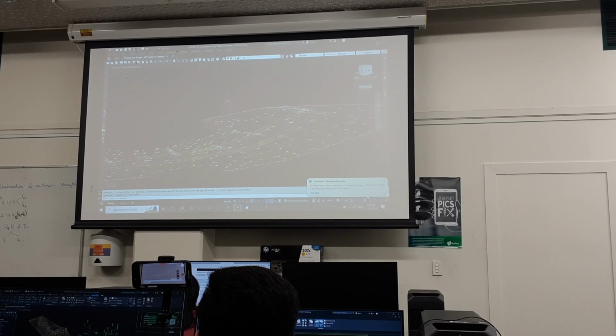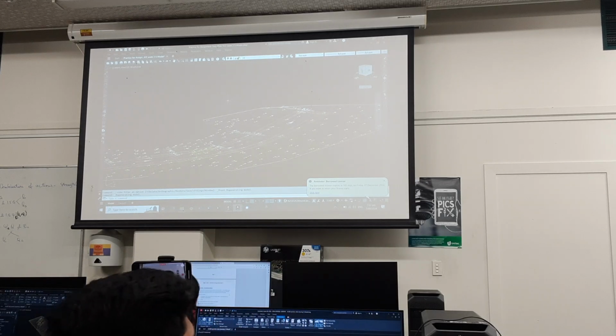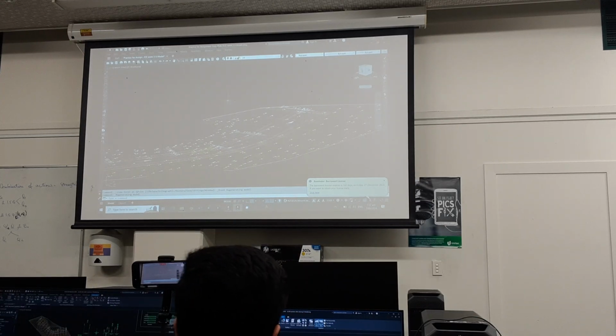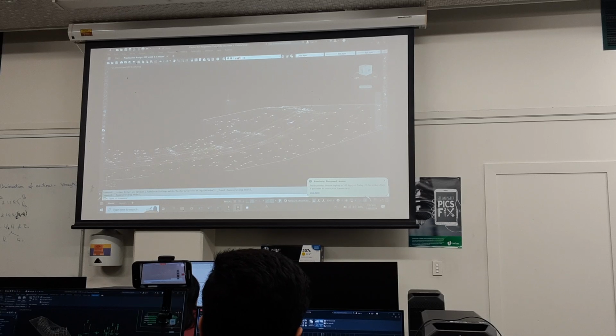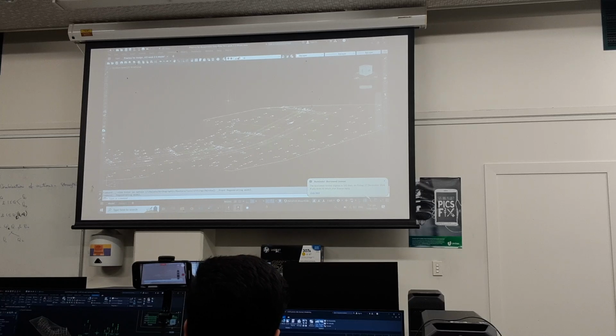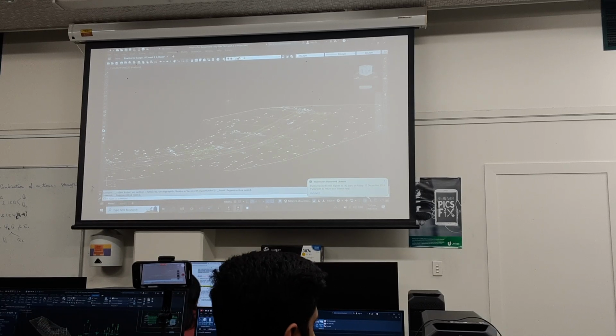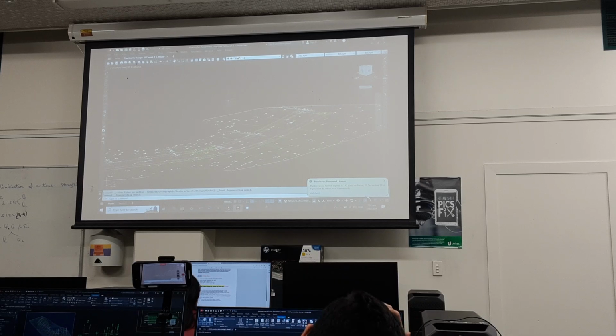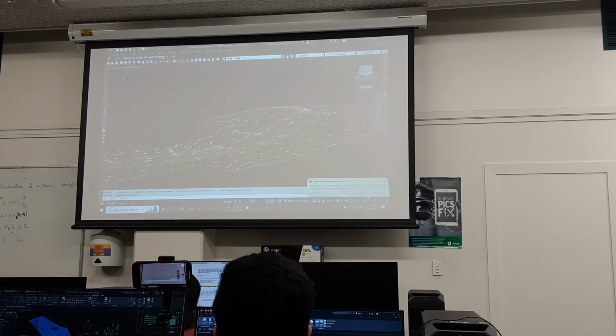Remember those lights that we clicked on before? On the left hand side we turn things visible on and off, and then do the export into AutoCAD. It will save you quite a bit of time in terms of deleting it from AutoCAD. But you'll need those lines on there for the proposed plan. So how you deal with that is up to you.